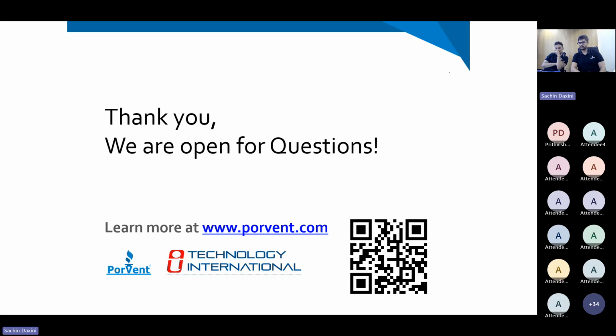Okay. Next question: is the vent capable of handling gases such as EMC and DMC without affecting its performance or causing degradation over its lifetime? Yeah, so the membrane is absolutely inert, especially the PTFE membrane options that we have. They would not degrade. As a matter of fact, this is why those regulations are slowly creeping in, because these are forever polymers and they don't really degrade much.